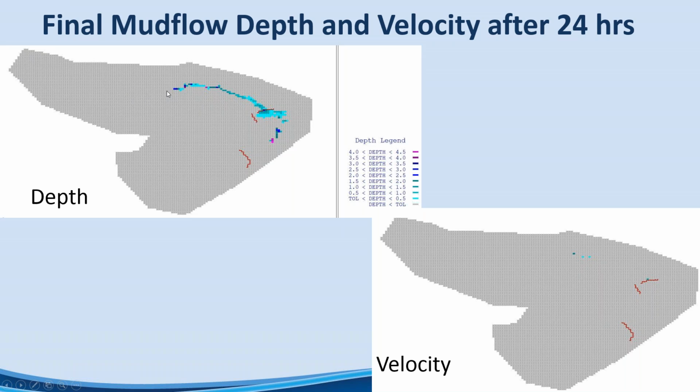And it's going to be about as accurate as you can do because you know the volume in the reservoir. Because you know the volume of the reservoir, this is the best any hydraulic model can do. If the model conserves volume, you can roughly predict the area of inundation fairly well. And so, whether this extends a little further downstream or more deposits up here depends on your initial saturation levels, and if you did any laboratory analysis or you're just using the mud flow parameters here, whatever it is you did, you're going to see some variability in this.